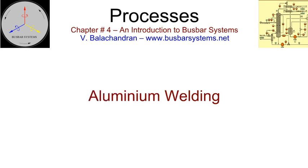Aluminium welding. Welding of aluminium sheets and bars is now an established practice in the bus industry. Aluminium laminates are also manufactured by welding the solid tabs to either end of prefabricated laminates. Aluminium welding is extensively adopted for the manufacture of conductors and enclosures for isolated phase bus, segregated and non-segregated phase bus, gas-insulated bus, high-voltage open bus in switchyards, and high-current open bus DC connections in metal extraction plants. Tungsten inert gas, TIG, welding and metal inert gas, MIG, welding are adopted for the welding of aluminium.